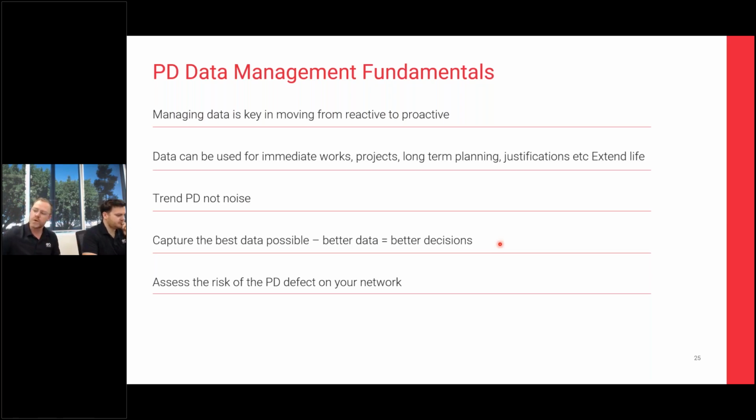That gets the worker in the morning, turns on his Ultratev +2, puts it onto the Wi-Fi, and the internet will give him basically the surveys that you want them to perform. Then they go out in the field, they go to those substations or ring main units, wherever they are, pad mounts, outdoor yards, and they get walked through: take a TEV reading here, take an ultrasonic reading here, and all that data gets captured by the person in the field. They just have to know how to capture the data and use the +2. Then at the end of the day, they put their instrument back on the internet. It uploads all the data back to the cloud where you can analyze it, trend it, compare it to other things, and there's a lot less handling of the data.